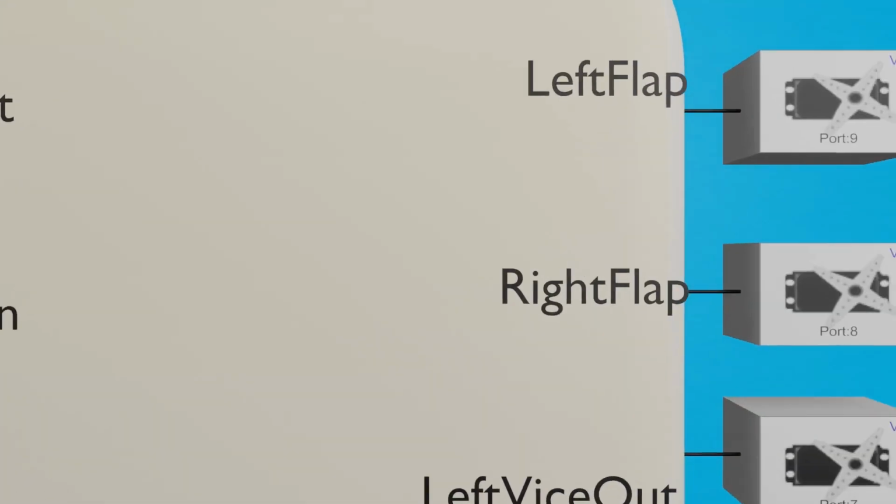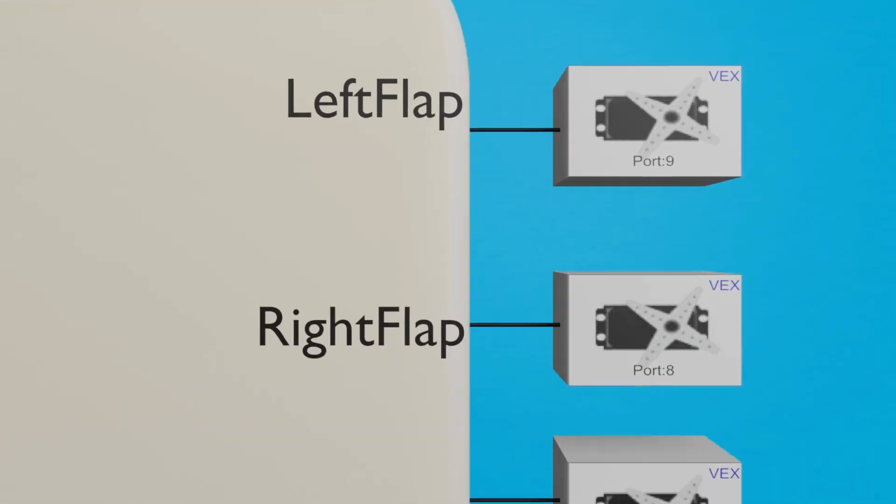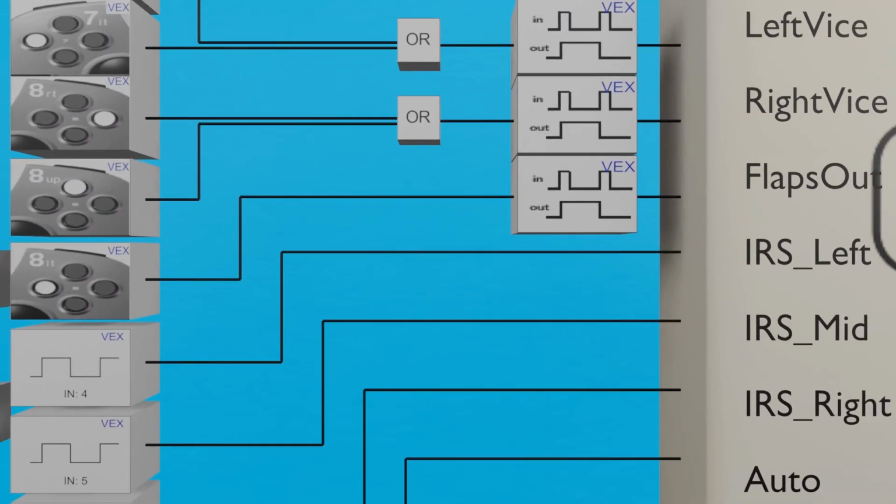Each of our robot's vices is mounted on a flap so they can be rotated 90 degrees. Each flap is rotated by a servo, and both flaps are controlled by a single button. A latch is used so that the button's value is toggled with a single press. The remaining necessary interactions for these functions take place within the state flow discussed later.